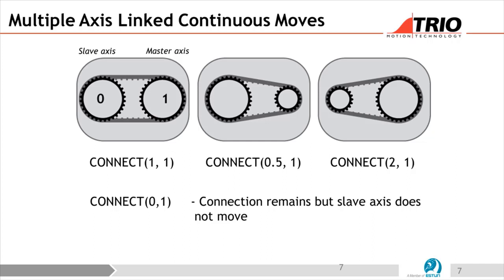If I've got an input axis, say the encoder on these modules is 4,000 counts per turn, and my slave axis is, say, an Eston drive with a 23-bit encoder, then one count on that wheel is not the same number of degrees of angle change as my 23-bit encoder on the motor. So in that case, I could probably use quite a high ratio, and it actually would be okay, just because I have this crazily high resolution on my slave axis. So effectively, you just sync two encoders.